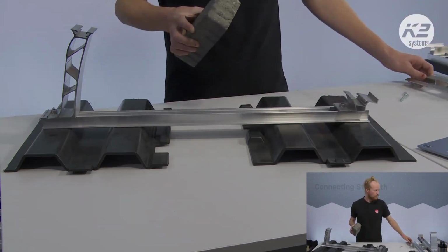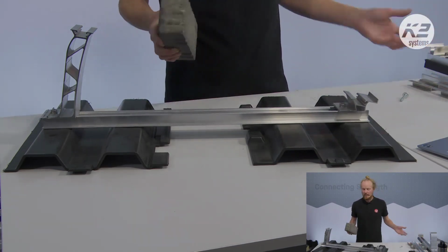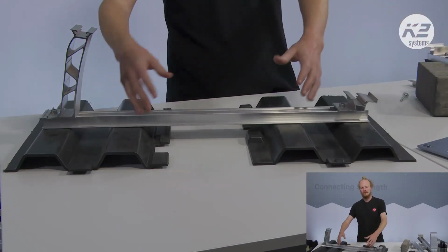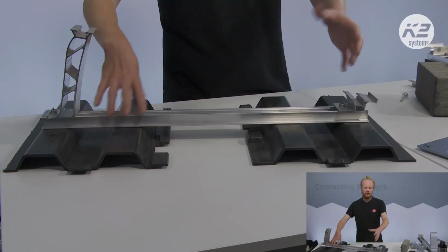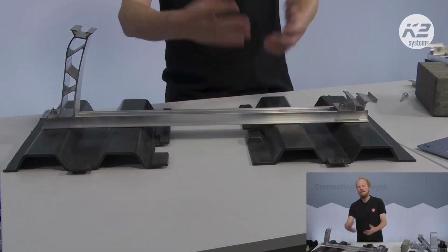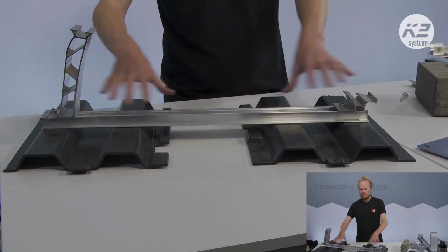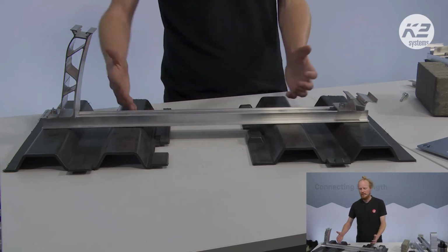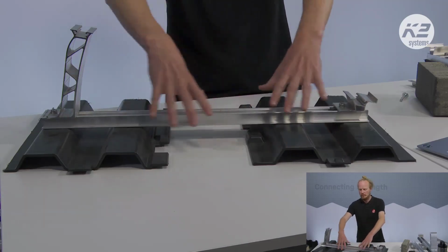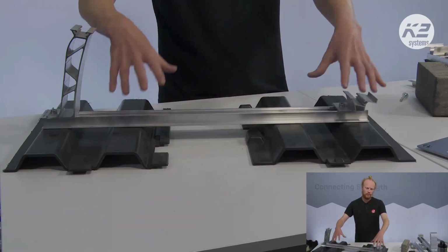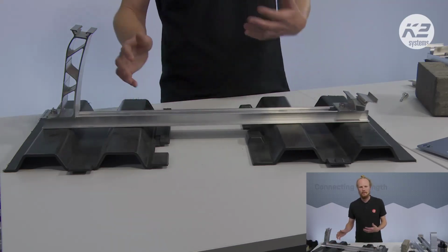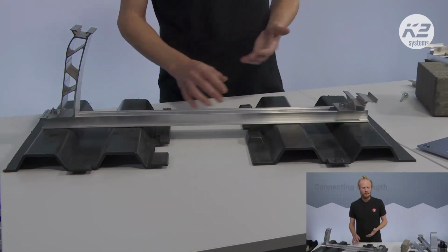So, or you can also use additional PE plates. And exactly, as Vladimir just suggested, you can also put more PE plates on the roof. As we said before, if this is a representation of 20 kilos and this is a representation of 20 kilos, and we have enough space, so here it's just a really small sample, but if we have enough space for another PE plate in the middle, then this whole section is represented by 60 kilos of ballast, and in most cases that's going to be plenty.